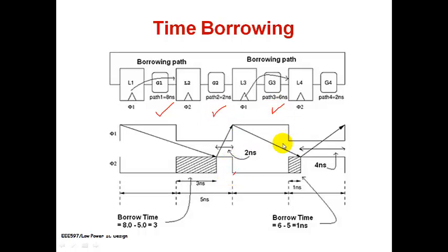And for the next thing I want to have 6 nanosecond. So I will start from here. For the 6 nanosecond for the path 3 it would go with this 5, and along with 1 nanosecond borrowed from here I could take, and with the use of the 6 nanosecond what I have realized from here to here, with the 5 nanosecond here and 1 nanosecond borrowed from this point, totally 6 nanosecond I am able to complete this job also.